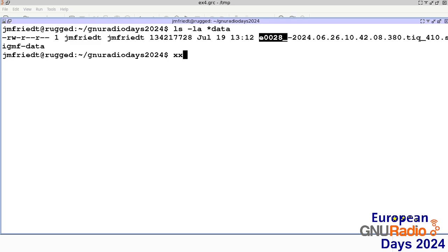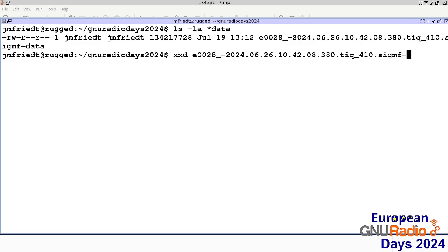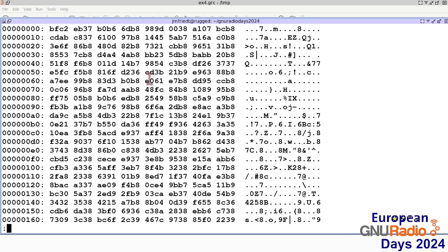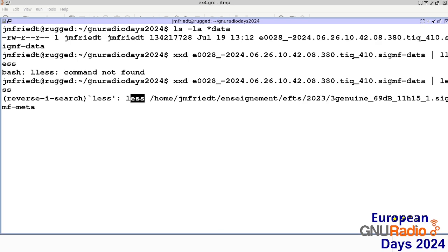and that doesn't tell you anything about how these data have been stored. If you just look at the binary file here that was provided, it all looks like random quantities because it's all floating point or integers or bytes. There is no way of knowing from the data file what the file format is. So what GNU Radio is promoting is to use a meta format, and this meta format is, for example, a